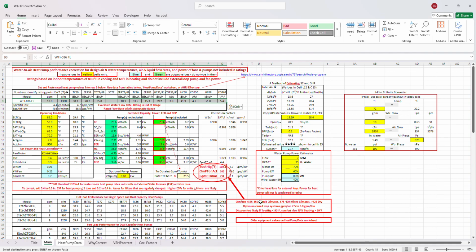So let's mess with this a little bit to see if we need to do anything. Let's see. No, it looks pretty good. See, we got 365. Oh, we got a real good SHR. Let me kick this up just a little bit, maybe to kind of match what was done before. So 382, 208, nice, 0.75. But see, the EER didn't change much. So EER is 12.4. This is still at 0.08, okay? So you can see this is what happens when you have a variable speed machine running at full load, okay? Now, what we're going to do now is one more step.